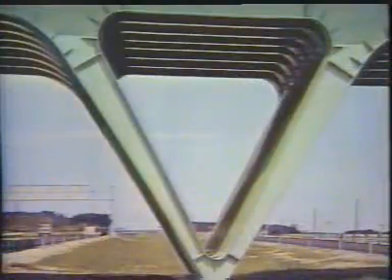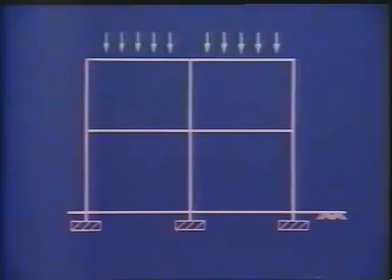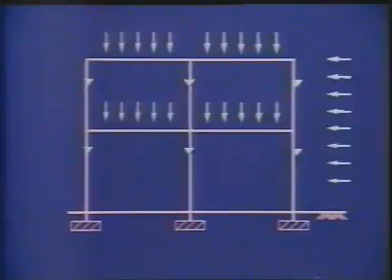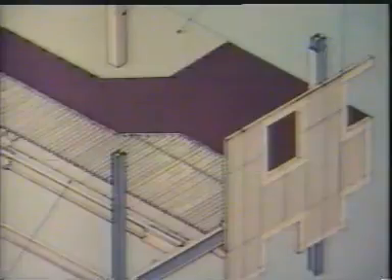In buildings, the primary purpose of the columns is to transfer loads from the floors and the roof to the foundations. They hold the floors apart. They also carry horizontal loading from wind and even from earthquakes. Their secondary function is to support the cladding covering the building so that the enclosed space is weatherproof and suitable for its intended purpose.